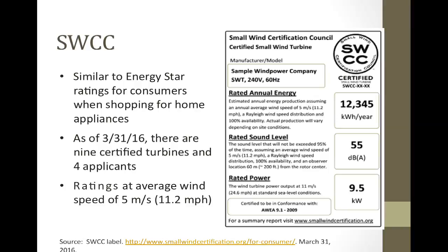So if the turbine's hub height is 140 feet, then I need to walk at least 60 feet away from the base of that tower in order to measure that sound. If I'm closer, and sometimes even further away, the sound may be greater or less. So this is where it was measured from, which can be pretty important.